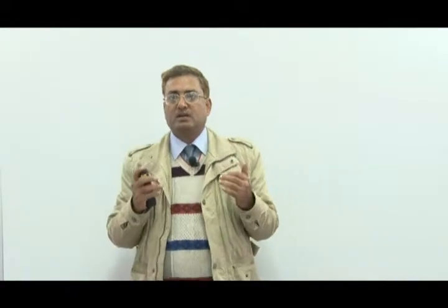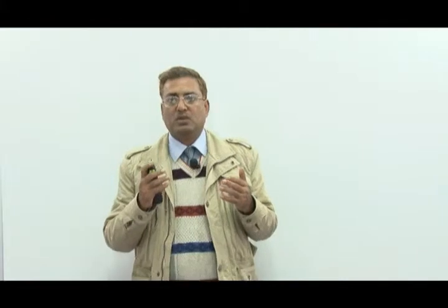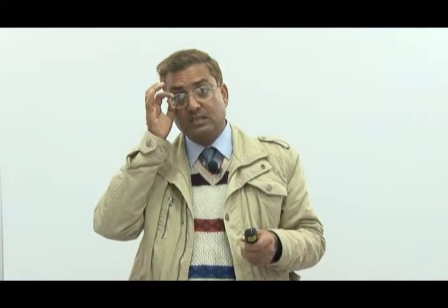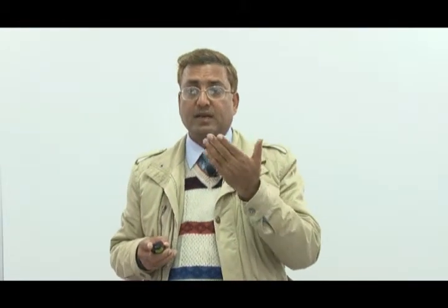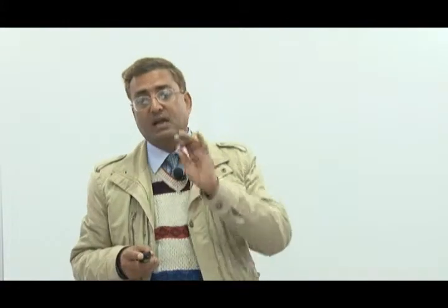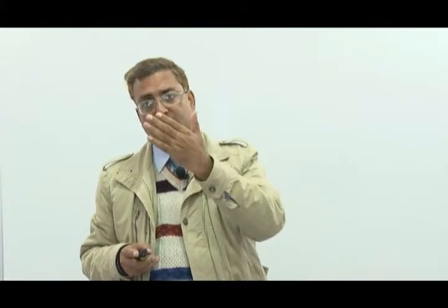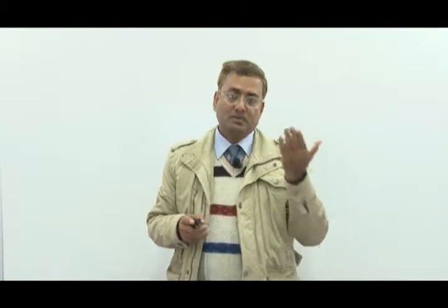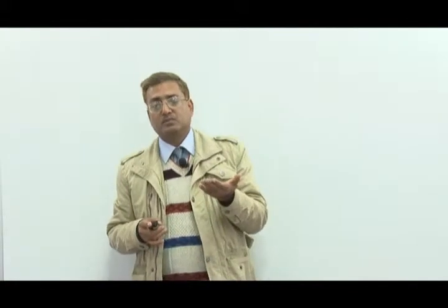So note that we have the following relation for the shape functions: Ni at node j must be equal to delta ij, where i and j are 1 to 8. This condition was valid even for the 1D problem and for the 2D problem, as we have seen.